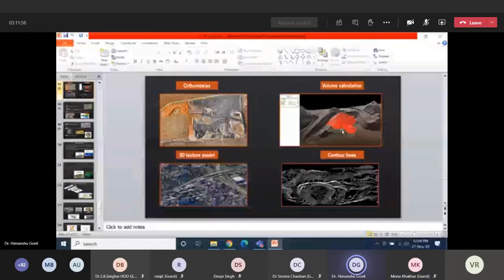These boundaries are shape files, in terms of GIS files. So you can change these sections to the upper level as well as to the lower levels if you want. But the drone will automatically calculate the altitudinal changes. Once the changes are there, it can calculate. But you have the possibility to change these boundaries according to your own need. Okay, okay.